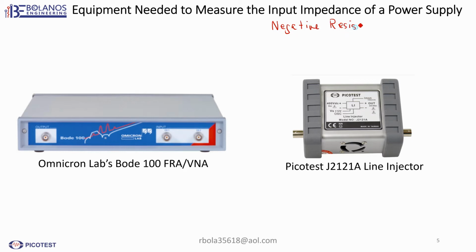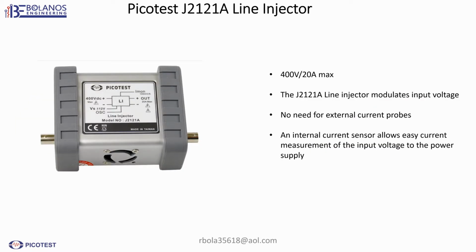And then when you put them in parallel and solve them, we end up with 68.9. So this should be at least close, negative 69 ohms, let's say. This should be the negative resistance that my flyback should measure, at least close to it.